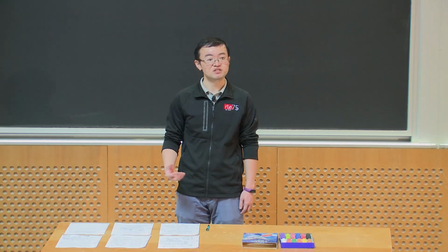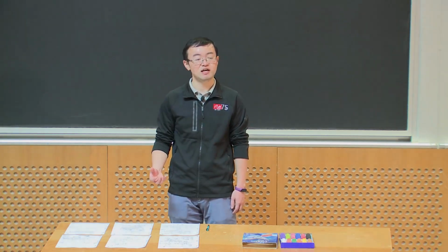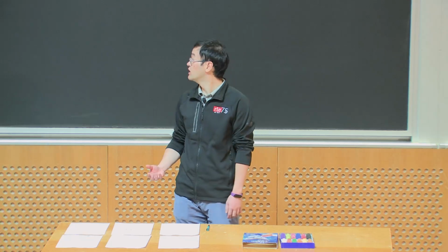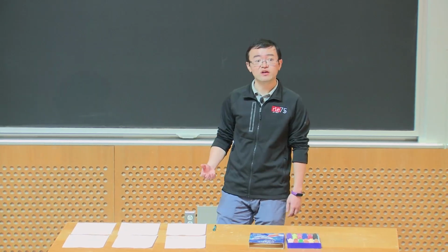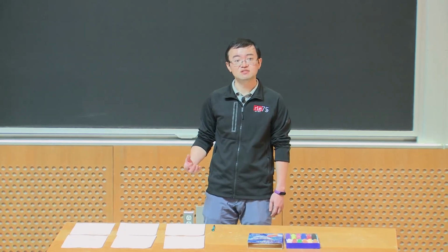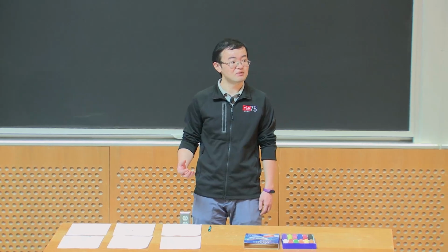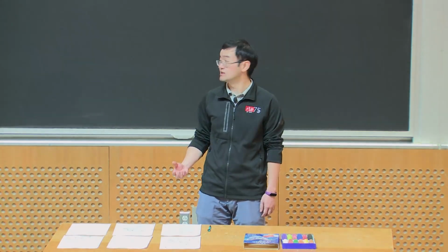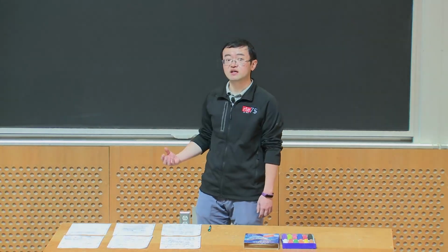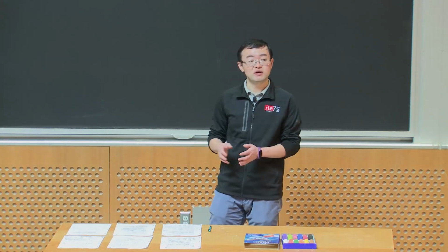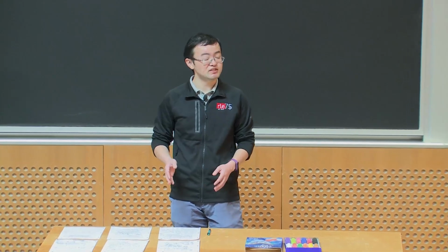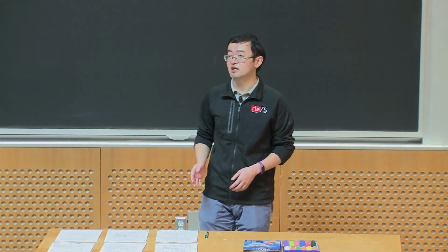For example, the BJT can only carry positive current, but the MOSFET can carry both positive and negative current. When the switch is off, the off resistance is very big, but there could be some leakage current. The blocking voltage also has a polarity. For parasitics, we usually have a parallel capacitance in parallel with the switch, and some switches will have an anti-parallel diode inside of them.